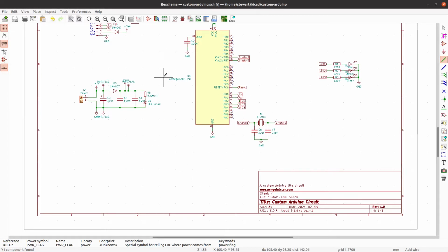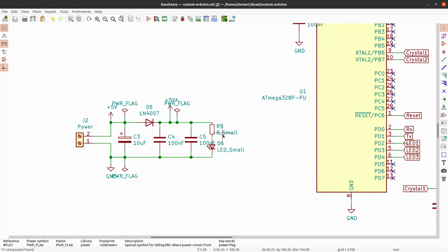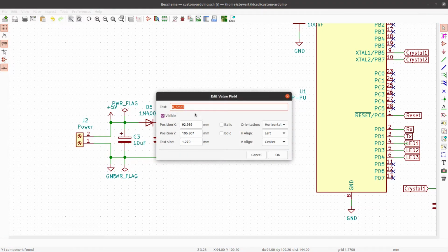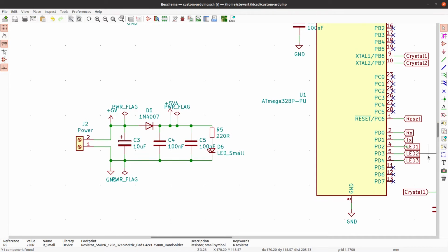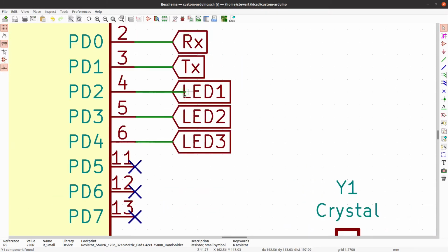So I did notice while I was in there a couple of things that I might want to change. One, I haven't changed the name of that, so that's 220 ohm SMD. I could put SMD in that if I want, but it's going to be obvious when we get onto the next stage. Well, I just noticed as well that doesn't look good. I don't think it's a problem, because the rule checker would have picked it up.